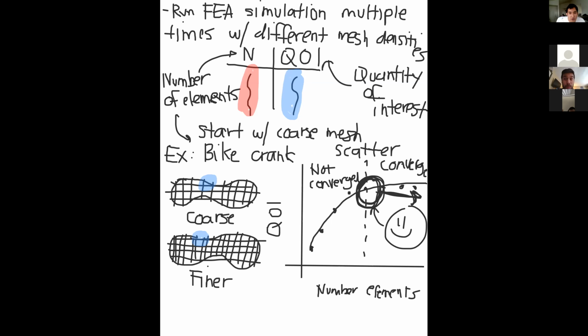So you're never going to get it to be exactly the same as you refine. It really depends on your industry, but some of the numbers that I've seen are things like 5%. 5% is pretty much the max, but if you can get it less than 3% or 2% relative change, then that's usually pretty reliable, at least from what I've seen. But of course, if you're working in aerospace or something with much closer tolerances, then it's going to be tighter than that.